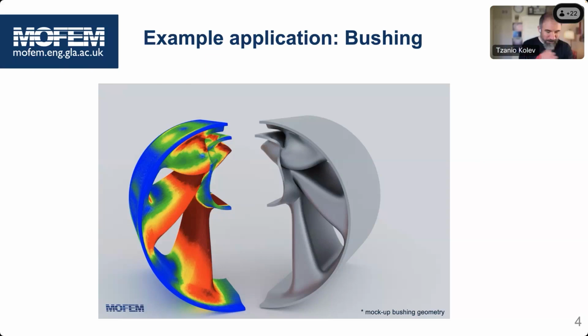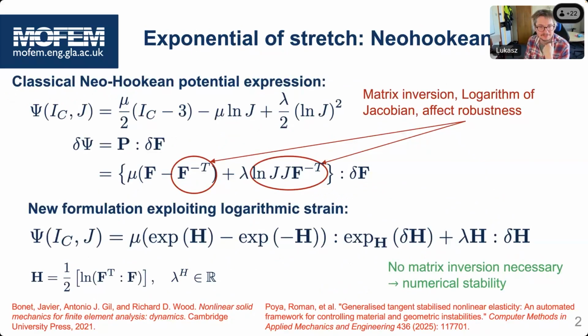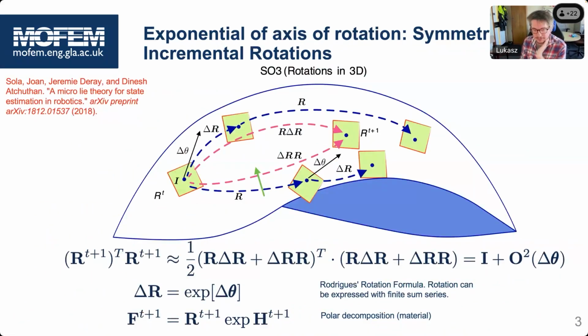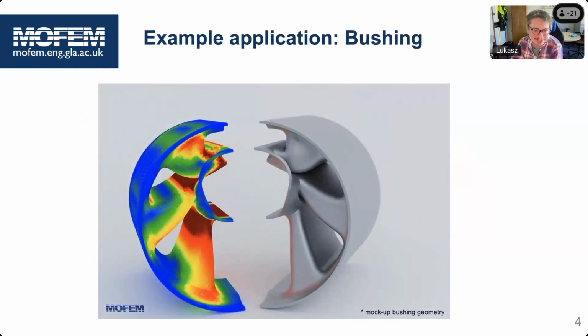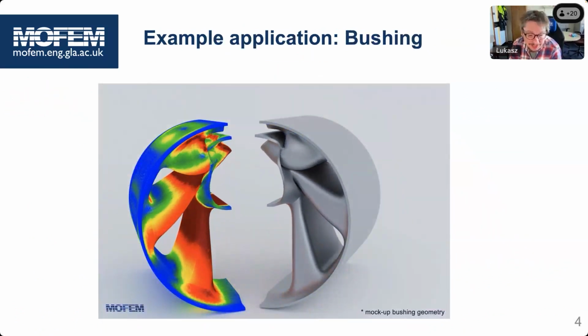Yeah, I mean, as you know, it's a trade-off because hexes are much better for GPUs. So yes, it kind of. But imagine, when you want to have something as simple as possible, because when you deform those elements, imagine what happens with the Jacobian at the different points. And then when you plug them into things like that, or even worse, when you have incompressible Neo-Hookean or Mooney-Rivlin, you want to have simplicity. This is my feeling, but I agree.